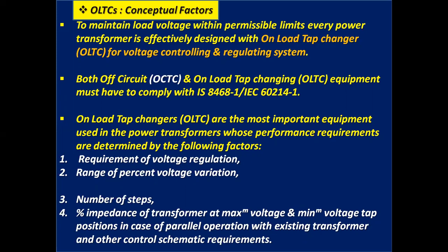Both off-circuit, that is OCTC, and on-load tap changing, that is OLTC, equipment must comply with IS 8468-1 or IEC 60214-1. On-load tap changers are the most important equipment used in power transformers, whose performance requirements are determined by